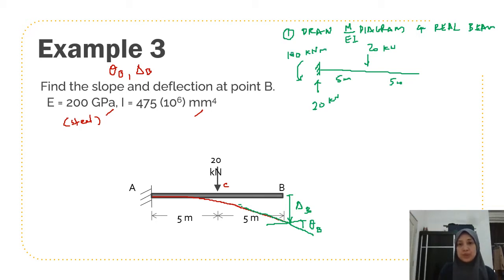Okay, so after that, you basically use whatever method that you have learned in the frame analysis. So if you look here, this is your tension is going to be above the line, and your compression is bottom. So basically it means that your bending moment diagram is going to be above the line. So if you do this, this is a negative moment, so it goes up and the value is 100. And then you don't have any load.